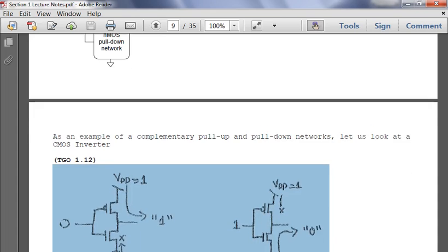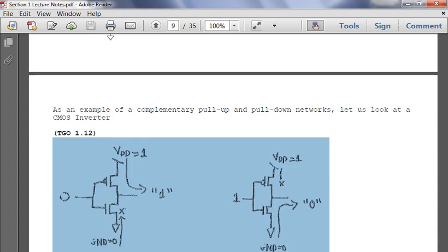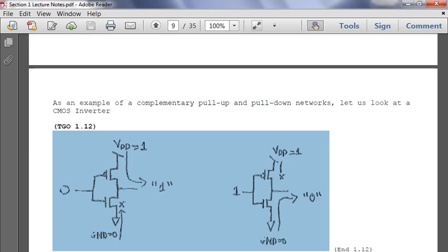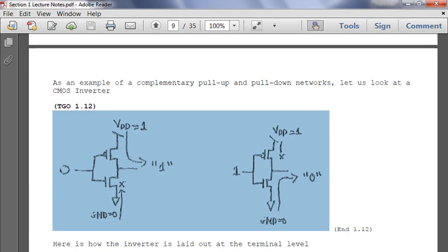Okay, and so I've already kind of alluded to this, but now that we know what's physically going on, this is the transistor. Again, for 0, we go to pMOS and nMOS. 0 is strong for pMOS, so it passes through, right? So now the channel is created in the pMOS transistor, and we're able to create the flow from supply voltage to output.